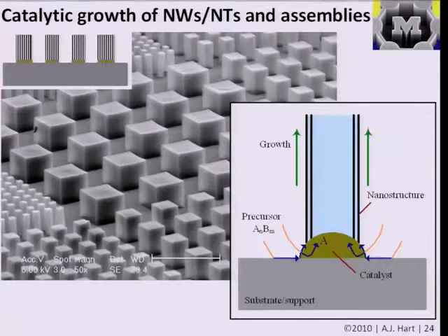And in some of these cases, we may, for example, start with particles on the surface which can be formed by that initial film deposition process, and then introduce a precursor. For example, in the case of growing carbon nanotubes, this precursor could be, say, methane or acetylene or ethylene, and because of the way the precursor interacts with these catalyst particles, the atoms may attach, migrate, diffuse, and detach, and also flow away in a way that is favorable for interaction to grow this structure.